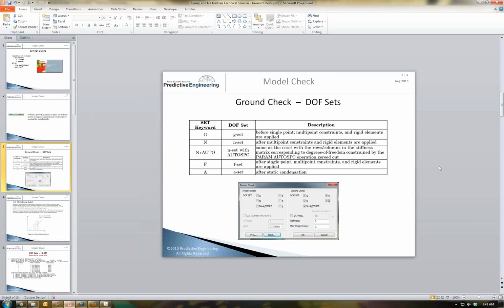Yeah, it's a good thing to bring that up, because in this documentation they say multi-point constraints and rigid elements when really the two are one and the same. In my next model, I've got both, and they result in the same sort of background mathematical setup. But we'll talk about how you would create a multi-point constraint or a rigid body element differently as far as managing your model. But in reality, like George says, they're not elements. You're not getting strain energy in your rigid body.